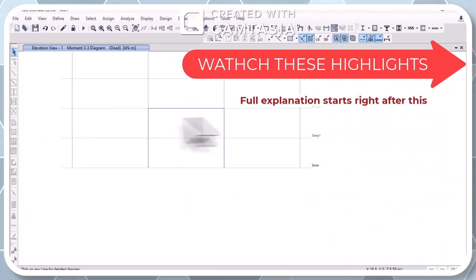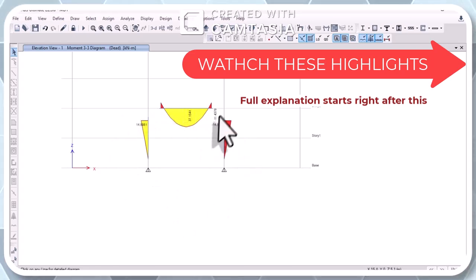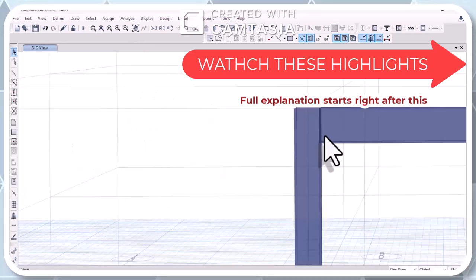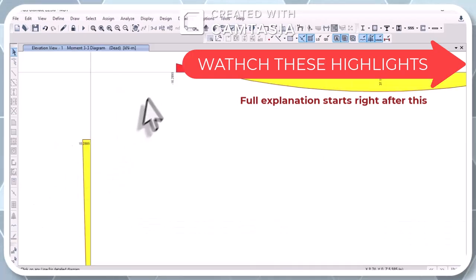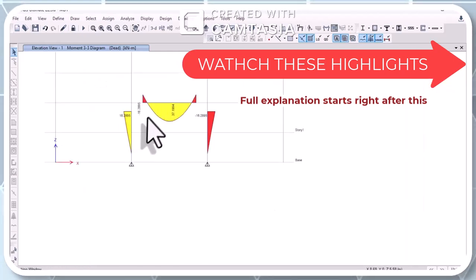So this structure is not going to be balanced. Okay, so this joint movement should be balanced. Okay, as engineers, you know that the physical connection happens at the column face. You can see the beams at the column face, not at the column center. This joint is going to be balanced. So if you go for the extra.